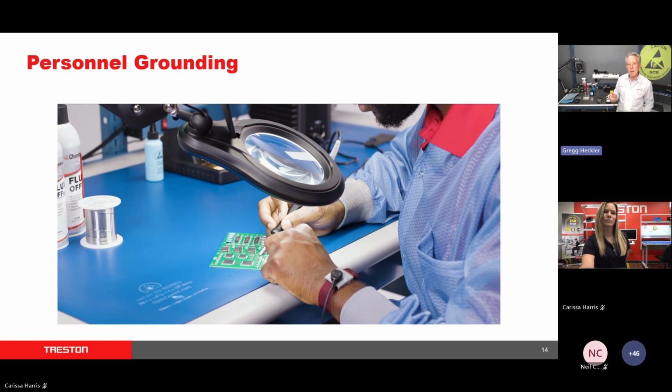And the way we do that primarily is by wearing a wrist strap. Secondary, if you're mobile, by having a footwear flooring system with an ESD floor. And right now I'm wearing foot grounders too, so I'm standing on an anti-fatigue conductive mat. We do it that way. But again, it's the same, keeping us at equal potential or at a common point to our workstation.